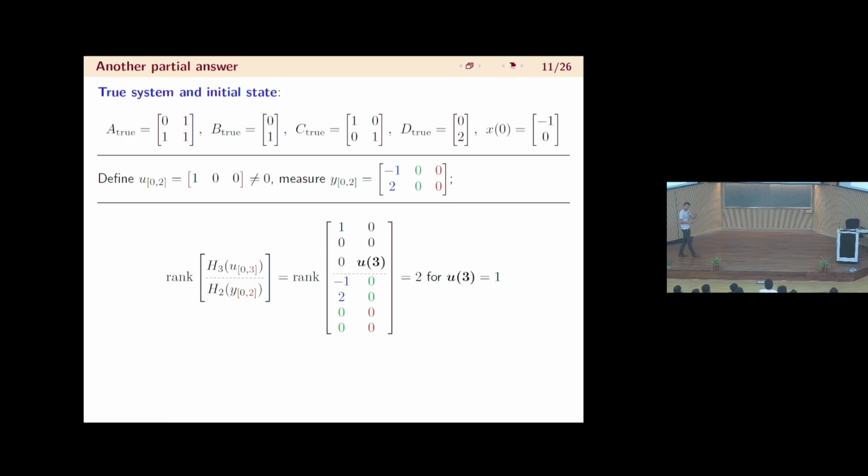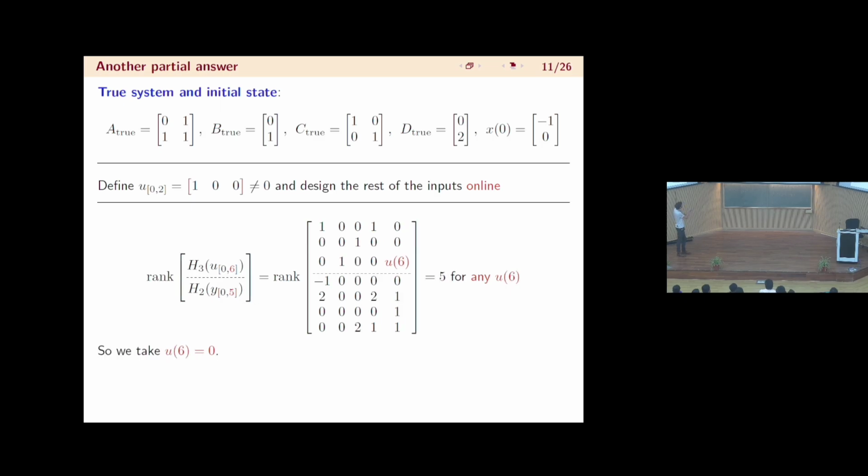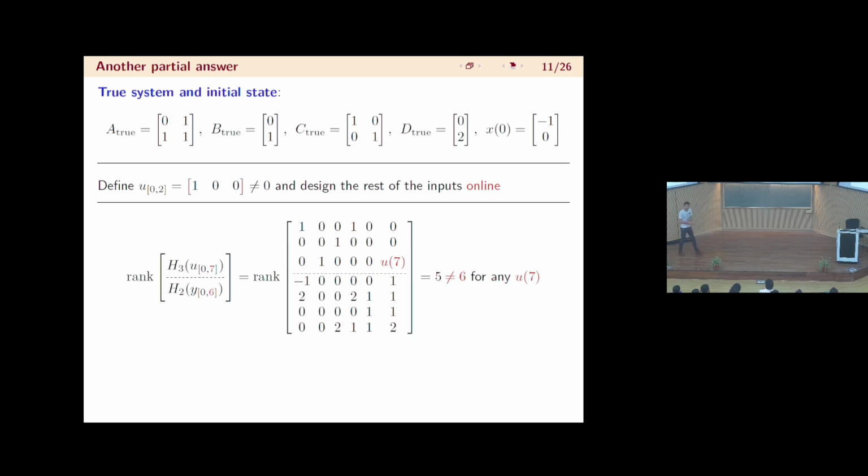But the conclusions in the end are going to be the same, because if I can make this Hankel matrix rank 5, then also when I add the final row of outputs, I still have a rank 5 Hankel matrix. So the reason for working with the slightly adapted Hankel matrix is because, of course, this last output depends on the last input. Just to give some intuition.